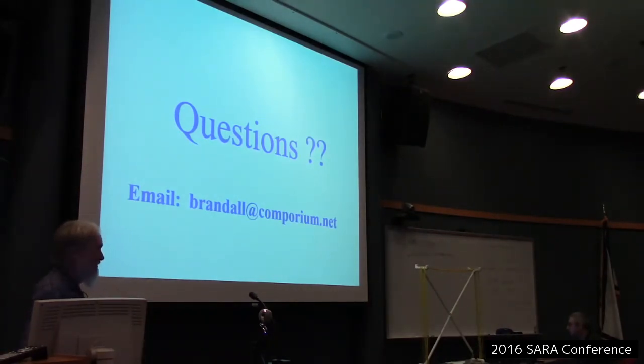Say something about clip-on ferrites. They're not all created equal. Normally if you put a solid ferrite sleeve on a cable when the cable is made, you end up with a nice complete ferrite. With clip-ons, the problem's not the ferrite itself, but some of them have a plastic clip that doesn't put enough pressure on it.